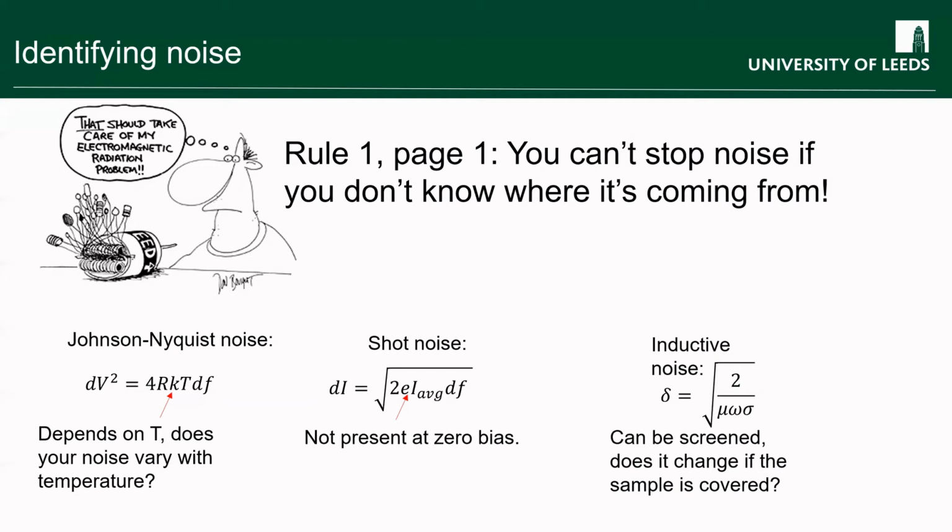And if you see that you've got shot noise problems, then again you want to think about, well, first of all, am I using too small a signal that I'm getting individual events? Is there a possibility that we could do the measurement with a smaller bandwidth, a longer measurement, so that you can reduce that kind of shot noise? It'll also help with Johnson noise. Can you do things to remove the tunnel barriers in your measurement?